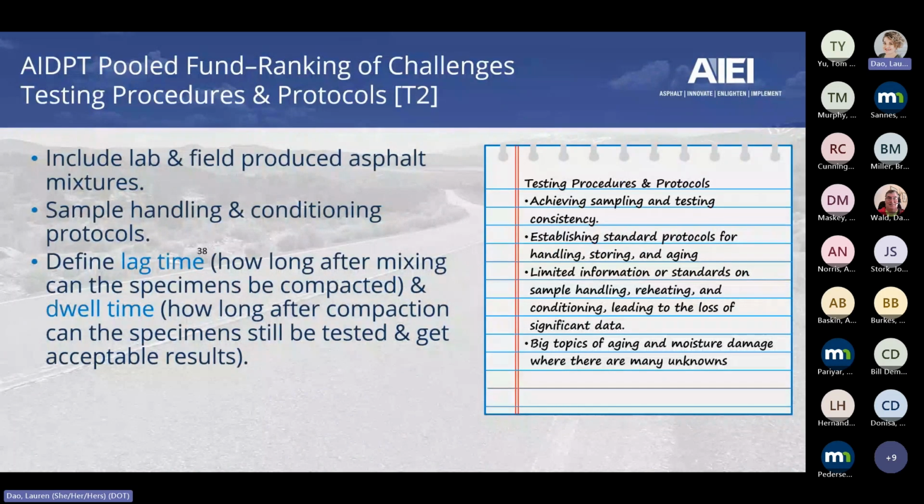The other aspect would be the testing procedures and protocols. A lot of the time when you refer to the AASHTO or ASTM standards, where do you end up? Typically it is how to run the tests, right? And then what to report. But a lot of the time, it doesn't describe how you need to handle your materials. What are your conditioning requirements? What happens when I receive that material? How long can I wait before I compact the specimens? Is that okay or not? Or once I compact my specimens, can I leave them sitting in the lab for a week, 2 weeks, a month before I test? Or do I need to put a limit?